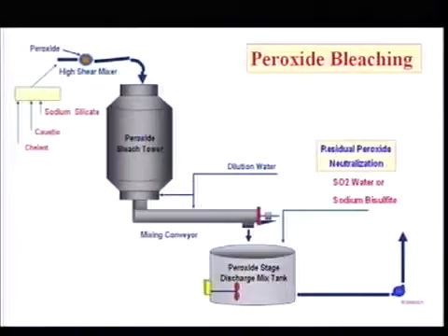And also if you are mixing with oxygen, you are dumping from top to bottom, oxygen can go away and stay in the top, so you won't have efficient mixing. So there you use the upflow tower. Where do you use the downflow tower? For peroxide. Here after mixing, you can just dump it.